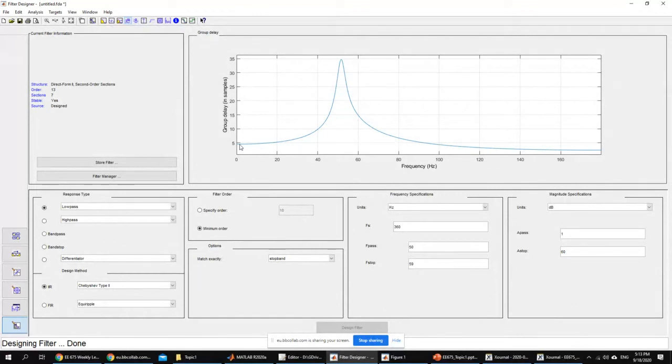what you might end up having is something called harmonic distortion, meaning that the frequency content of your signal, instead of being matched exactly the way it is in the input signal, might change a little bit. Most of the signals that we see are additions of multiple signals, multiple sinusoidal signals at least. So this variation in the group delay between different frequencies might cause some distortion at the output.